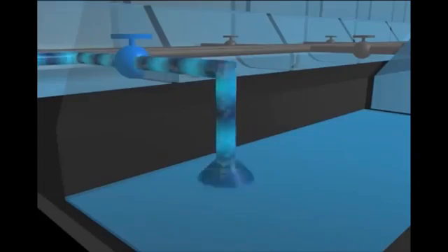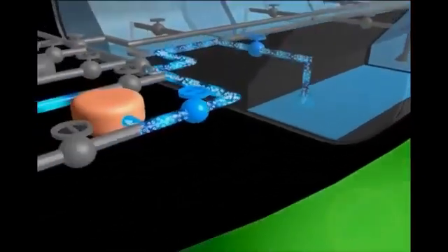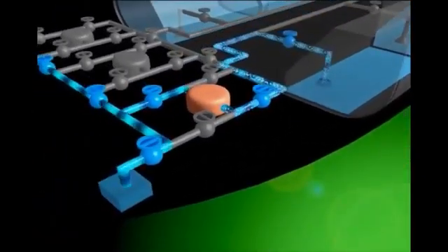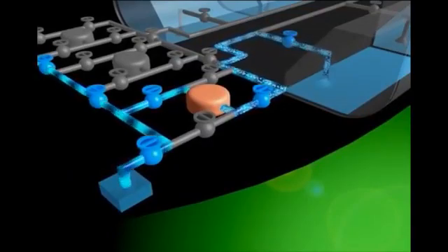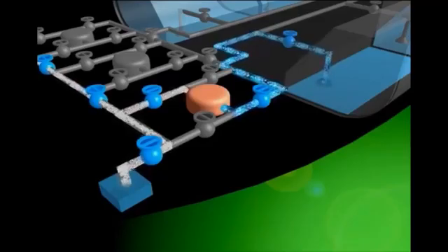If a pump draws in air while in operation, a noise is produced, and the amount of seawater discharge decreases, significantly lowering the pump's operating efficiency. Also, the amount of seawater being discharged will drop to zero in an instant once the pump has drawn in a large amount of air.